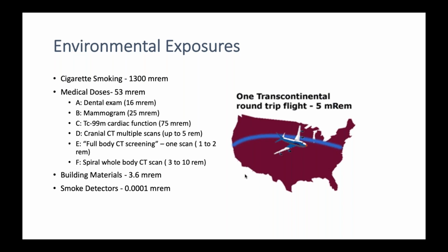How would you test a granite countertop for radon, do you think? Well, how do you test the basement for radon? Yeah, that little canister, an activated charcoal packet or canister, or you can have a track etch meter, a little device that hangs around for months. But most people use these little activated charcoal canisters. You expose them in the basement for a couple of days, and then you pick them up.